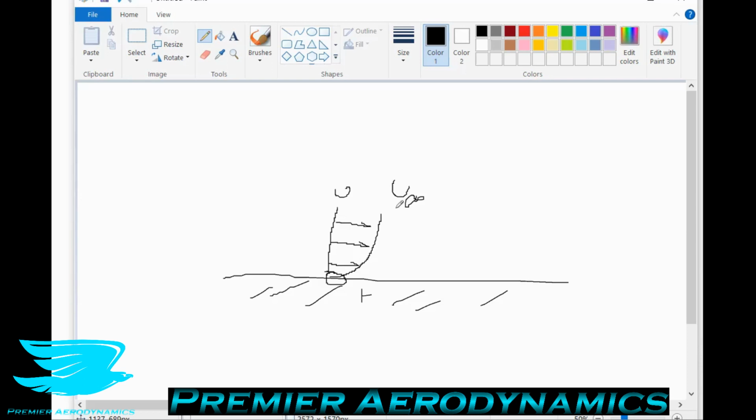So what we say is, let's say we have, just for argument's sake, a really big cell on the wall. So we don't have a very well refined zone. Instead of having many small cells refining this one zone, we just have one big cell, which is effectively what we have when we have a very high y plus value.